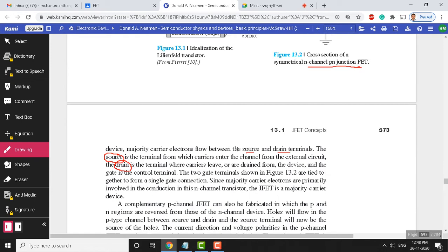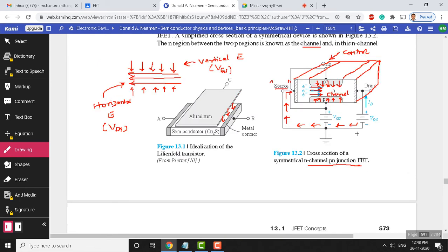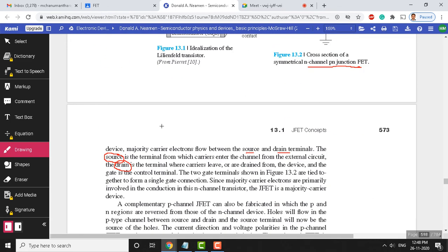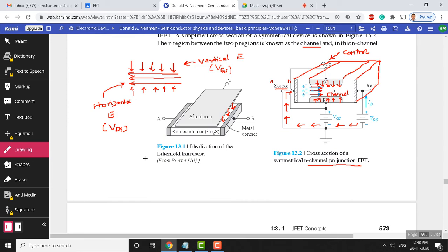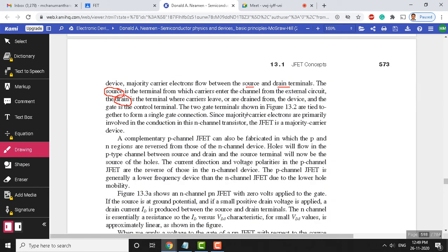But there are devices you will see, maybe in subjects like VLSI design, where we will discuss another gate called a back gate, and you will know the disadvantages of the back gate. But right now we only consider a single gate for FET. In fact, the FET is a 4-terminal device, but you are seeing 3 terminals here because it is normally short circuited. There is the source terminal, drain terminal, and only one gate because of the short circuit. Otherwise, MOSFET is a 4-terminal device.